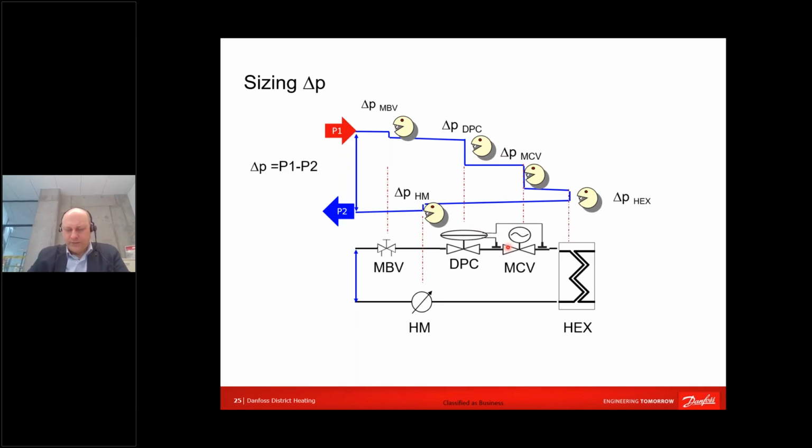On the other hand, we are now facing designers sizing flow based on the so-called breakpoint, when outdoor temperature is close to zero and when district heating temperature is fixed to some certain value, for example 70 degrees, then we may say that the flow will be largest.